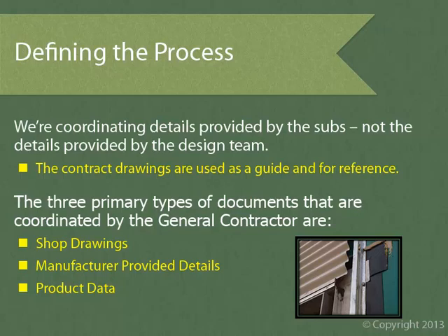What you see in this photo is a self-adhered sheet membrane, which is the black sheet, and also a green secondary membrane that are installed and awaiting the metal panel installation to continue on and cover them up. In the permanent building, they will be fully concealed behind the metal panels, which protects them from the UV exposure. But we need to be concerned with the UV exposure between the time the secondary membranes are applied and when the metal panels are installed.